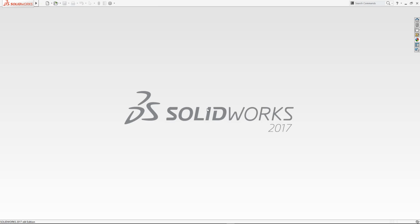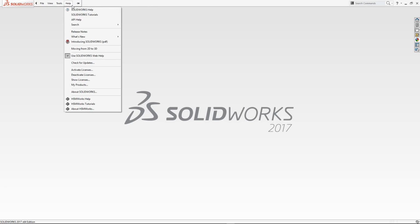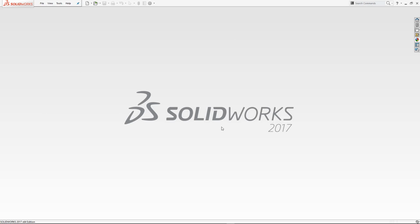So this is the basic layout. This little arrow here, when you hover over it, is going to bring out the main options. If you click this drawing pin, it will fix that there. I always have it there because I do use it quite a lot, and you never use all of this, so you might as well pin it open. So you've got all your options here, some grayed out, the main workspace, and then you've got your libraries pane down here.